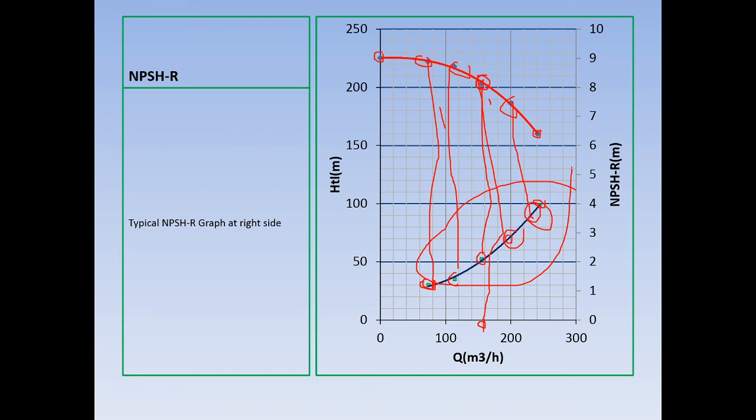And the NPSH available on your design or field installation is generally, to make it easier, the head of environment pressure 9.46 minus the distance between your pump and the bottom of the reservoir. Let's say 9.46 minus 3, and you have a remaining 6.46.